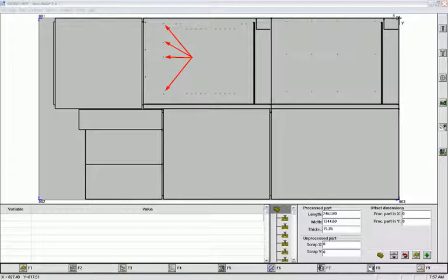Here we have a pattern of drawer guide holes for the drawer guide used in our base cabinet, and another pattern of drawer guide holes for our drawer bank. We can also use different drawer guides per cabinet. We have our adjustable shelf holes, door hinge plate holes, dowel construction for the cabinet's top, and a dado for our bottom's tenon whose edge is flush to the toe kick. We have our notches and tenons for our cabinet bottoms for blind dado insertion into the cabinet ends. Finally, our dado for the back. But we can have as many machining operations as we wish performed automatically, including blind dado mortise and tenon joints for selected parts.